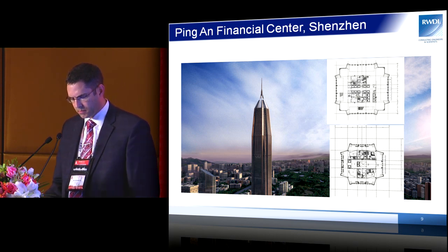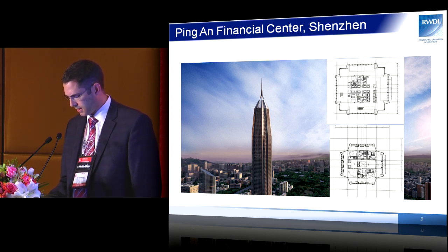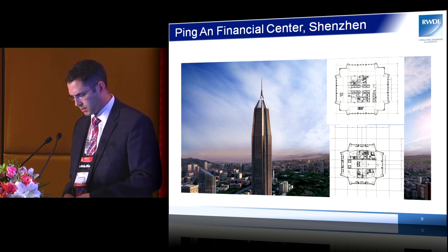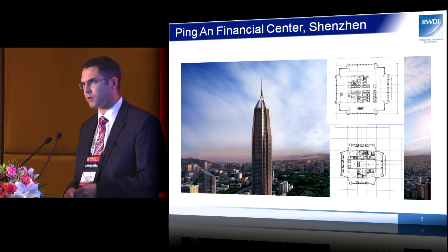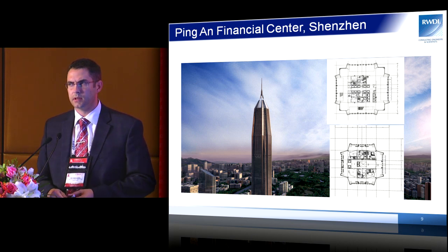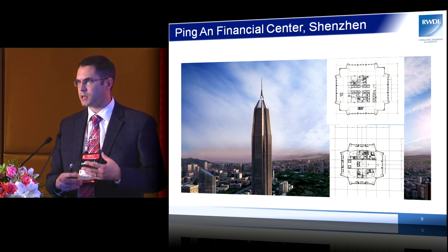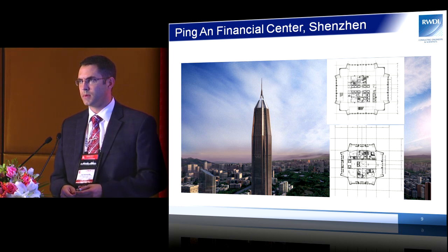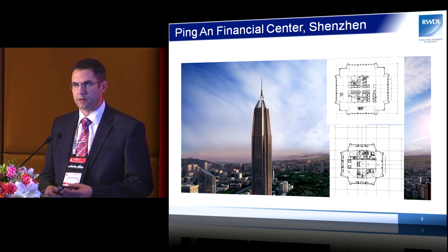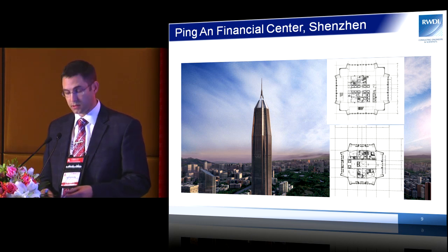So towards the bottom it has a detail like that, and then as it gets towards the top, it not only gets smaller in cross dimension, but that detail of the reentrant corner changes. So in effect, they're changing the Strouhal number relationship over the height of the building, therefore reducing the correlation of the vortex shedding.